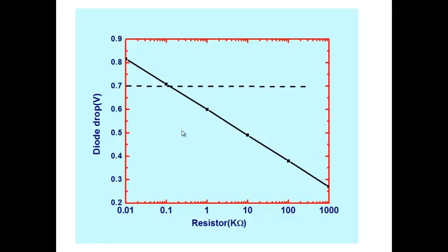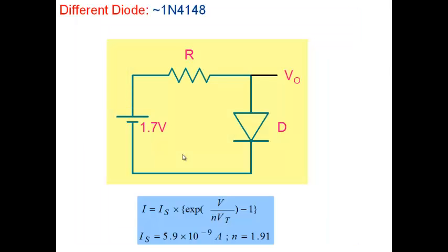There is a very quick check that you can do. Whatever circuit you're solving, let's say you've assumed 0.7 volt, and you get a value of current. For that value of current, just go and calculate this drop here. Use this equation. Where is that equation? Here. For whatever value of current, you can use this equation. So you solve a circuit with a 0.7 volt model, you get a certain value of current, let's say 1 microampere or 1 milliampere or 10 milliamperes.